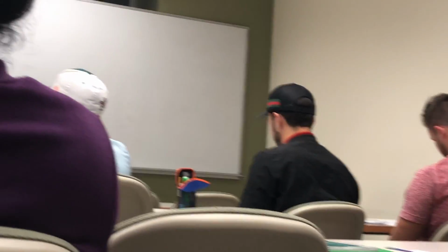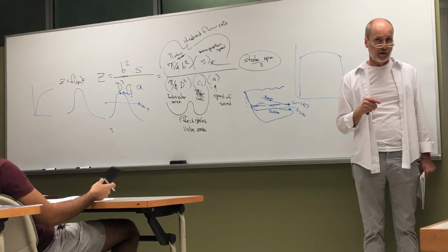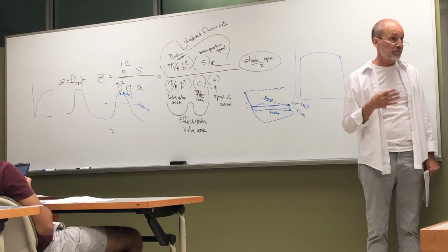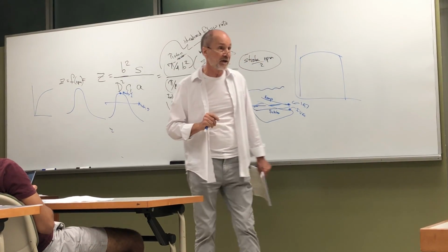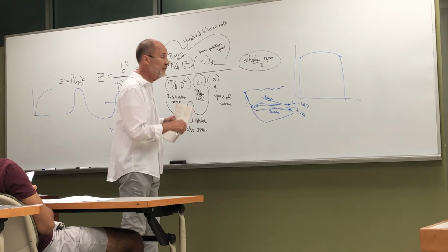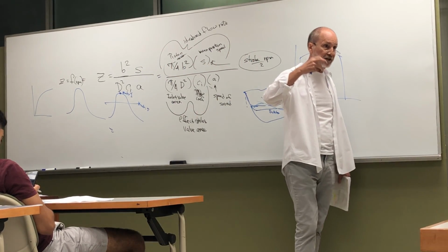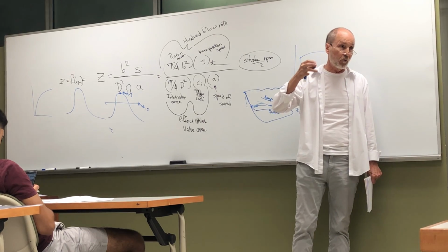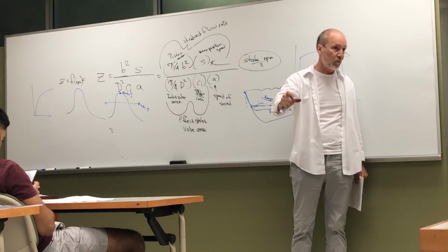For manifold injection, are Mach index numbers above 0.5 ever better for mixing? Well, more turbulence is always better for mixing, for any delivery system. As we transition from laminar, we don't have any of those little eddies that can tend to rip up a water droplet or tear a water film off the intake manifold wall.